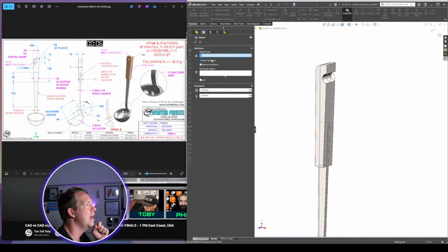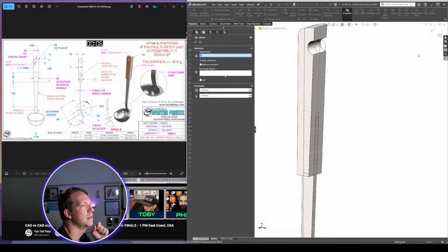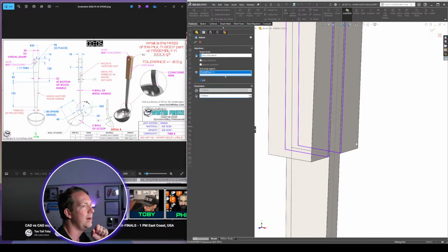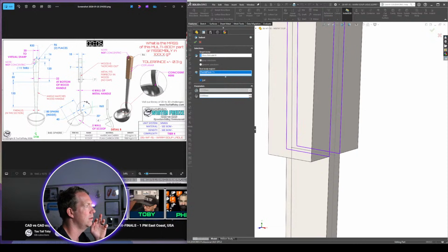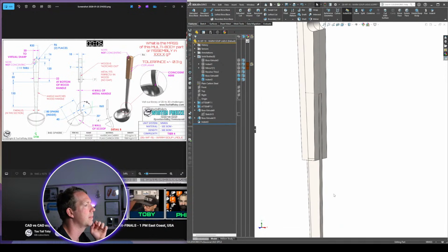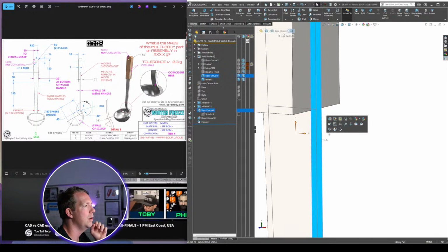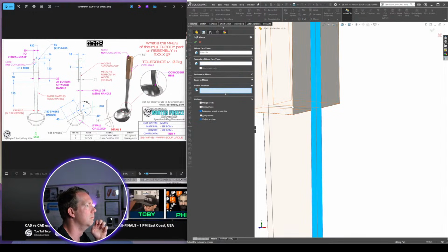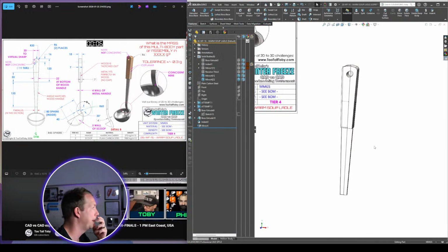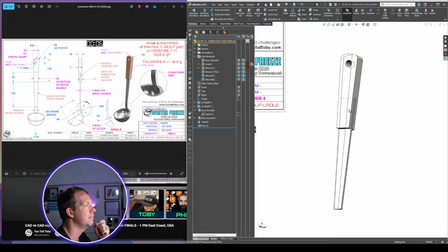So we can indent now. So this is the indent tool. So indent, target body is the outside, tool body is the handle bit at the bottom, and press cut. Now indent's really handy as well if you need a certain distance offset from the edge, like 0.5. It'll do it all the way around it. We don't need that, so I'll just leave it at 0. Okay, let's cut that for me. Then I can mirror, select both bodies and merge. Okay, beautiful. That seems really quick, right?